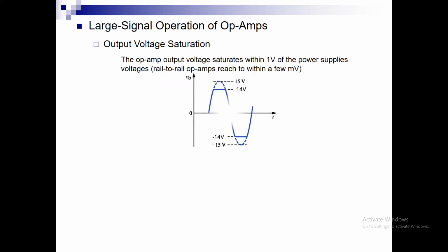First, my amplifier cannot output an infinite signal. يعني let us say that I find that the gain AV is going to be 16. Well, I'm not going to get VO equal to that. I cannot get it. I'm going to be limited by V plus and V minus, which are the output voltage maximum limits within which my signal can operate. ليش؟ لأنه أنا في عندي supplies I cannot skip. There are voltage drops in the circuit, so I really cannot satisfy the ideal gain.